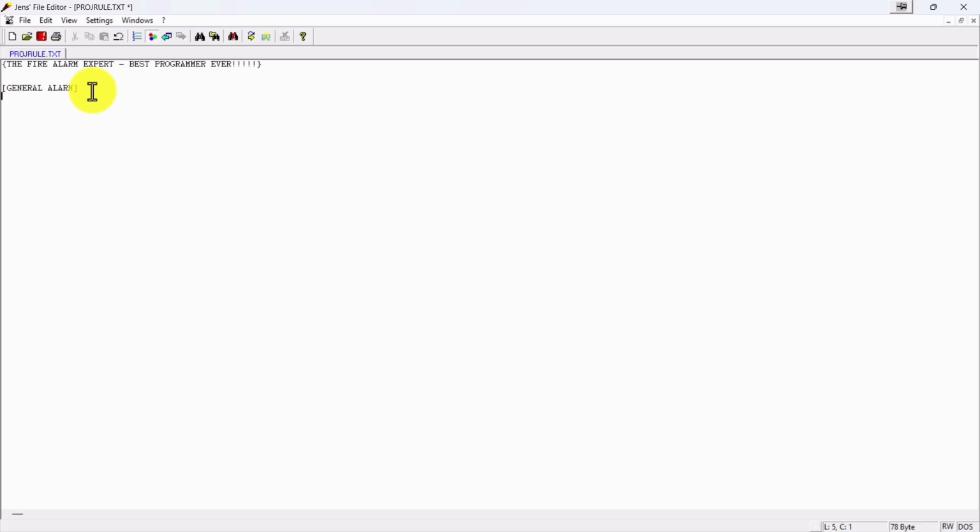So our input statement, we need the event. So what is the event that we want to do? Smoke detectors go into alarm, right? We can go alarm smoke, then we put the quotes. Now remember the labels we did, SMK_1 through 5. So what we want to do is we have to mimic that SMK_, but if we just put 1 and close it out, the rest of the smoke detectors will not work.